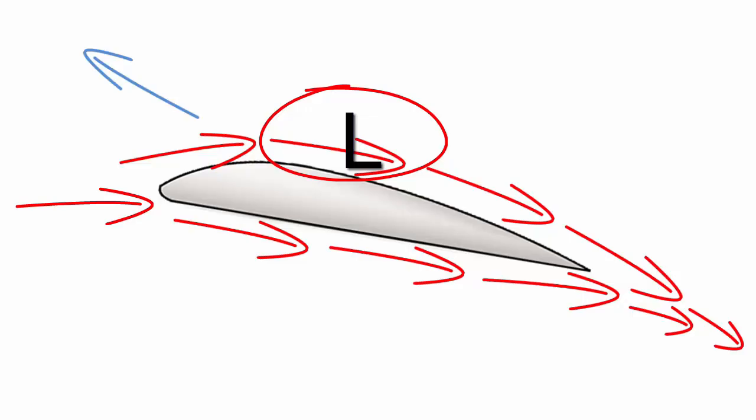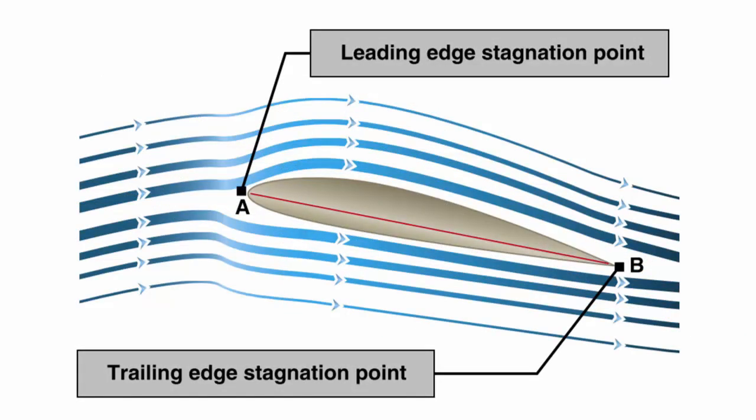Because of the manner in which air flows underneath the airfoil, a positive or high pressure results. At a point close to the leading edge, the airflow is virtually stopped at a stagnation point, and then gradually increases speed as it moves further aft.